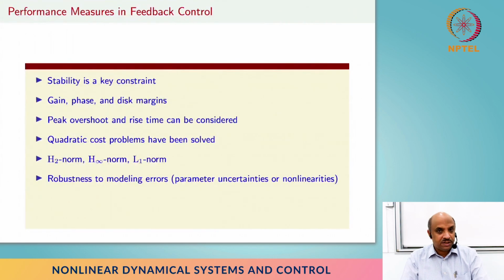We can define similar norms in the nonlinear systems case, but it's not that easy, right? So in that sense, you can treat them as open problems to be solved in nonlinear systems in terms of minimizing any of these norms. Right, the H infinity norm, as we'll see, we will address the extension of that in nonlinear systems to some extent, but not the other ones.